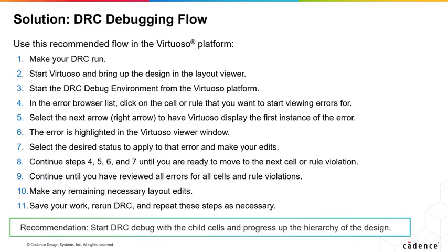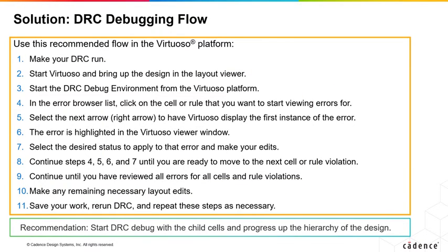Here is a recommended DRC debug flow in a standard Virtuoso platform. Please read through the lines. It is always a better practice to first array the DRC list on the complexity scale, and then address the most complex violations at the beginning. Even if you need a significant change, say a cell movement, they are not overlooked till the last moment.